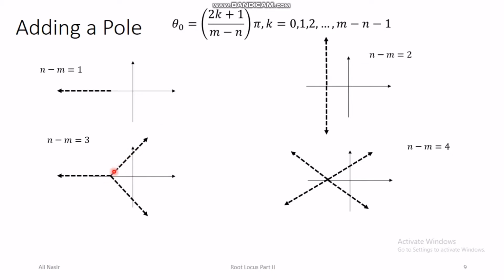So two of the poles have the root path going to the right side, the right half plane. So in this scenario, you cannot afford a very large gain. If you have large enough gain, your poles are bound to cross the j omega axis and go into the right half plane if they are not already in the right half plane. Also in this case, poles move towards the right half plane even more quickly.